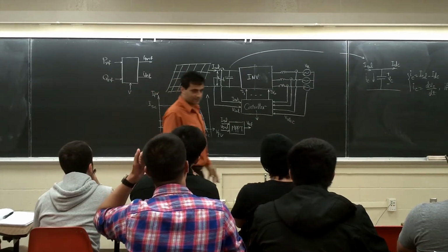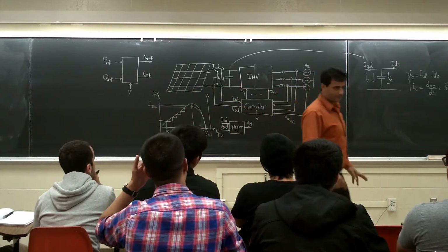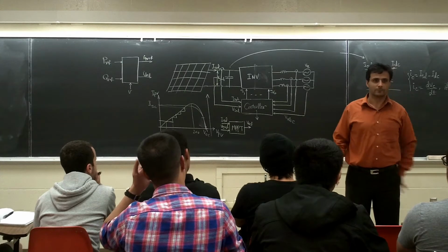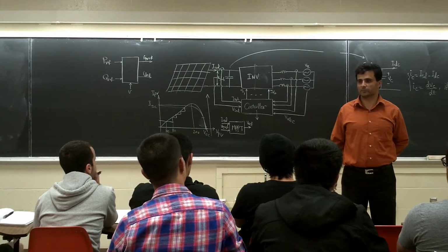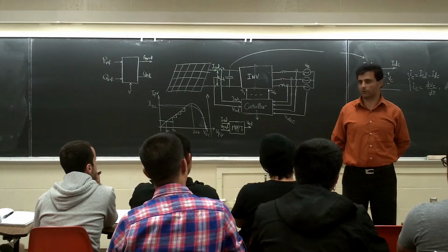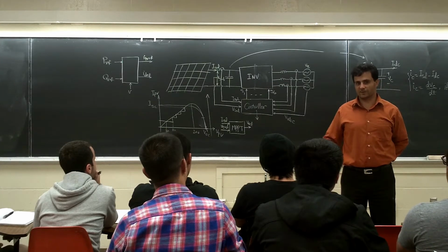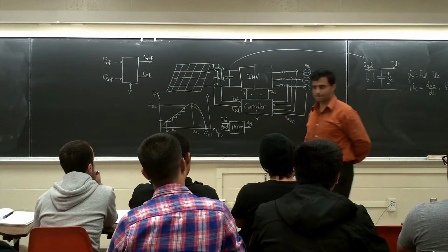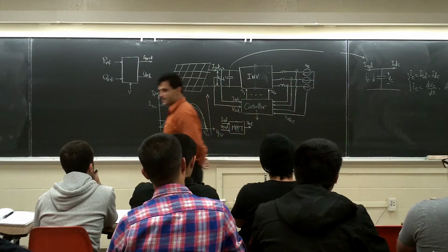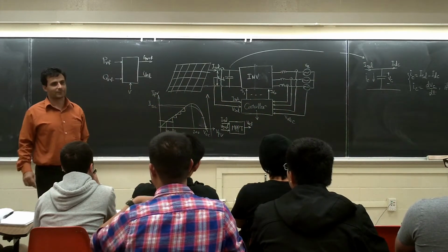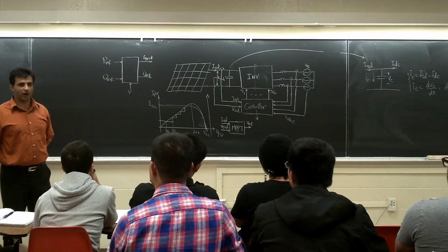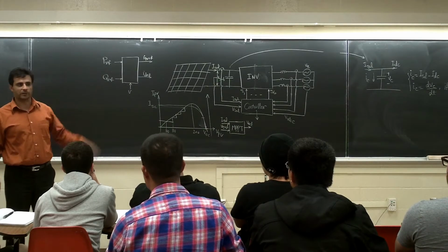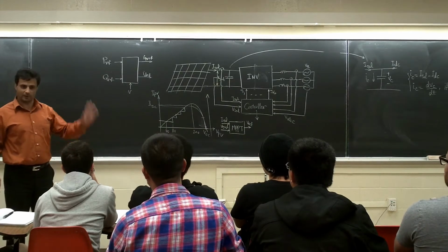We decrease IDC. Let's say IDC was 10 amps, now it's 5 amps, for example. The DC voltage was 100 volts. What is happening? P is VI, right? Let's assume the inverter is ideal, 100% efficient.